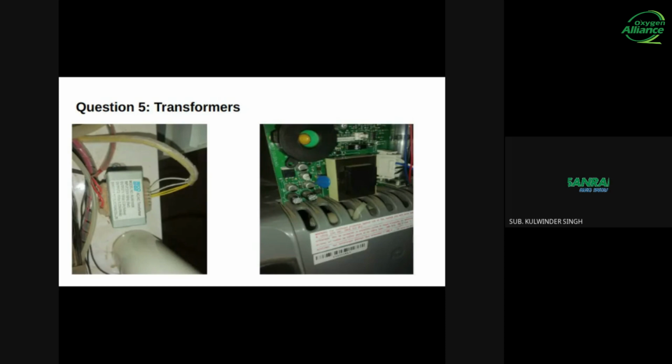So in conclusion, replacing a transformer with another of the same voltage rating is not a straightforward solution and must be done with caution. It is important to consider factors such as current capacity, impedance, and physical differences to ensure the replacement transformer is compatible with the electrical system and meets the specific requirements of the application.